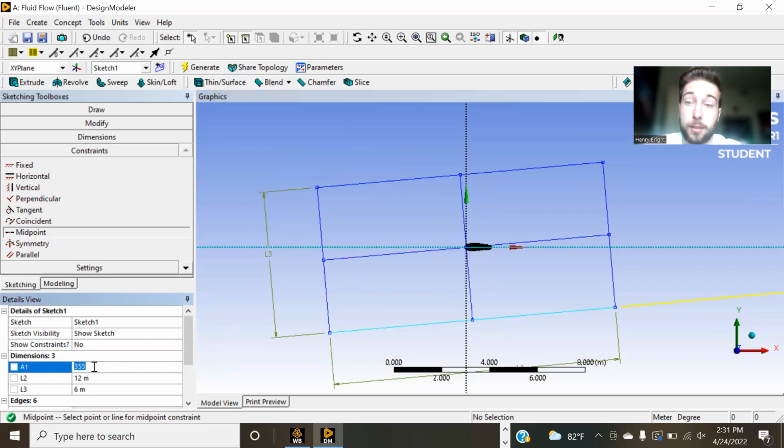So in this case, it's 355, which actually just means that it's inclined 5 degrees from the horizontal, which you can see. And this is a positive 5 degrees, because the airfoil is flat, your free stream velocity is coming this way. So it's essentially like the airfoil, if you were to look at it with the velocity being horizontal, you can see your airfoil is basically inclined upward. So that's a positive 5 degrees angle of attack.